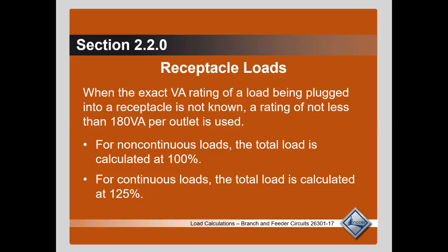So say, okay, if I rate this at 12 amps, no, is that 2 amps? It's 1.2 amps is what it is. So 1.2 amps, then essentially I can put 13 outlets on a 20 amp circuit. So, now you can multiply 13 times 1.2. So that comes out to 13 times 1.2 equals 15.6 amps.